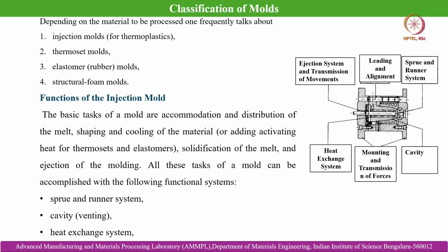Here the several functional parts of the mold are shown: cavity, mounting and transmission of forces, then the heat exchange system, then the ejection system and transmission of movements, then leading and alignment, and the sprue and runner base system. These are all the essential components of injection molds.